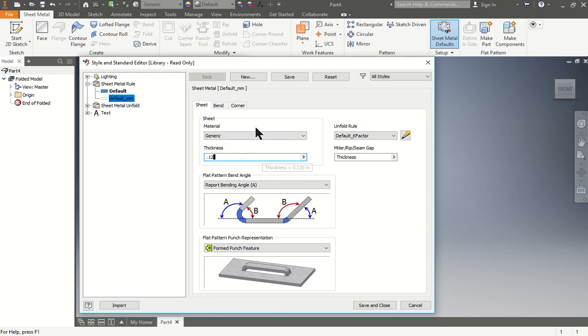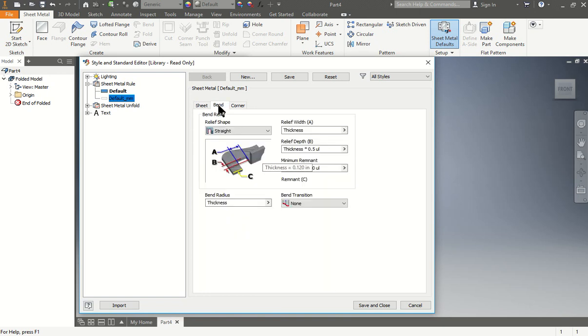We're going to click on the bend. And we're going to make sure that in the bend, we leave it as straight. And we're going to do transition. We're going to leave it at none. Okay, this looks okay. Relief, sorry, in the relief one, we're going to put it to round. My bad. So now we rounded the edges over here.